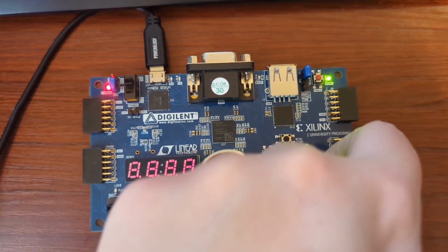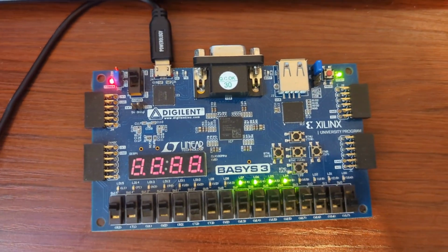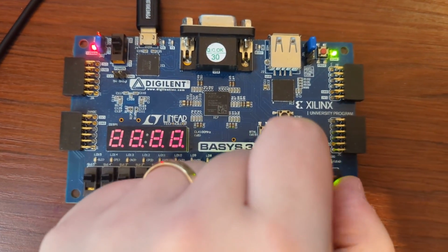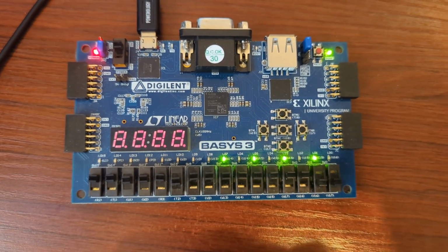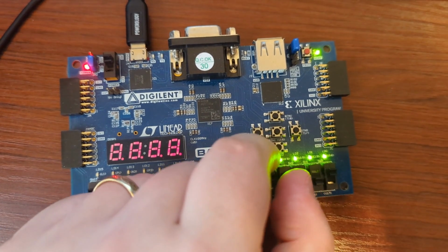Now, when I flash the board, I can hit the switches and my RAM values are displayed on the LEDs. Very cool. I can also look at the report from Vivado and see this actually used the hard block RAMs on the chip, which is what I want.